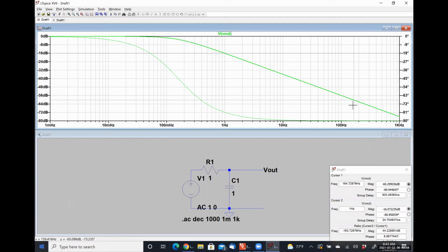That's how you design things to guard against electromagnetic interference and EMPs. 60 dB is kind of the benchmark, and anything you can do over that is fantastic. But once you get to around 120 decibels, which means your signal power is 1,000,000 times smaller, past that your numbers are effectively garbage because you can't really measure beyond that threshold.